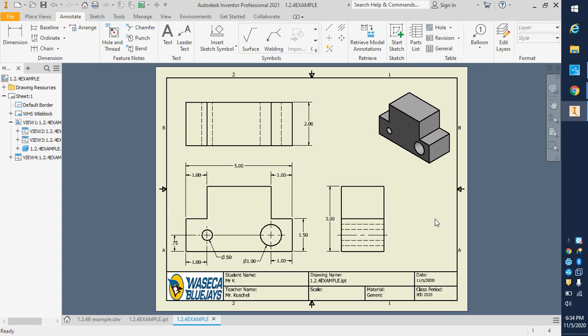So with that, I am pretty much done. I've got hidden lines in place. I've got center lines in place. I've got dimension lines to show me size and location of everything. Just like that, you have dimensioned. Okay. Most everything, again, done in the Annotate tab, Dimension tool, clicking on side, drag it up, line, drag that up. You want to have these lines line up and let the computer program work for you. And just like that, you've got a drawing made and dimensioned.